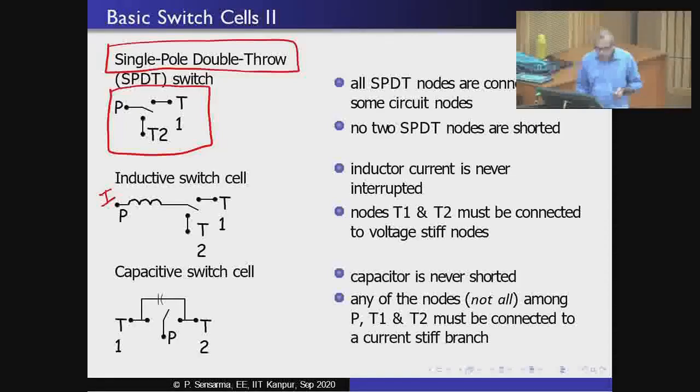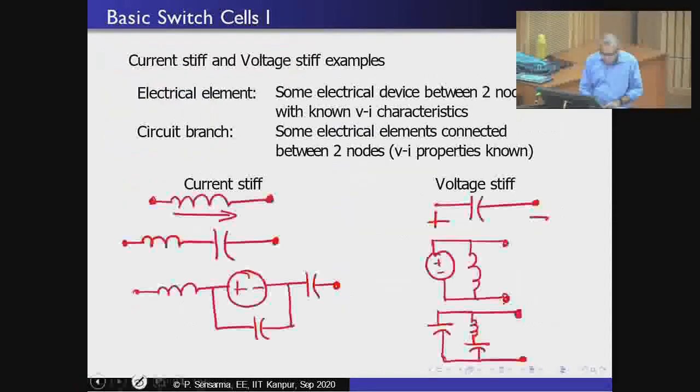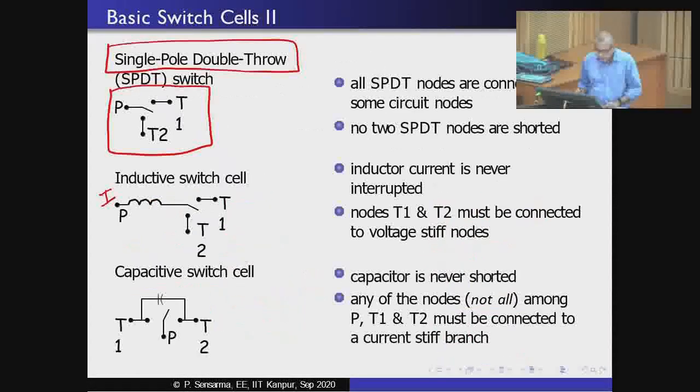Okay, that is the first construct using the SPDT, the inductive switch cell. You can also have a capacitive switch cell, where the capacitance or the voltage stiff element is connected between nodes T1 and T2.